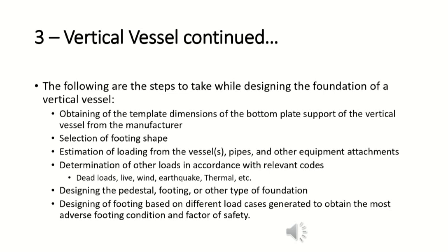Again, you also have dead loads, including those from the test and the operating fluid. You have live load, you have wind load, you have earthquake load and thermal load. 5. Designing the pedestal, footing or other type of foundation. 6. Designing of footing based on different load cases generated to obtain the most adverse footing condition and factor of safety.